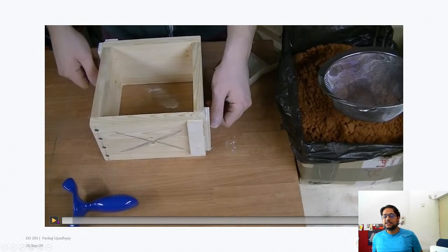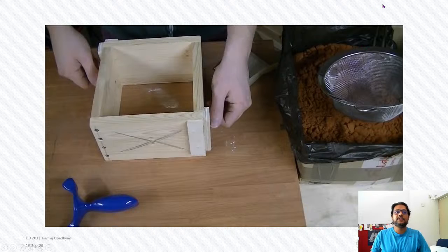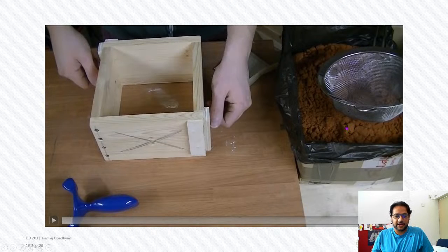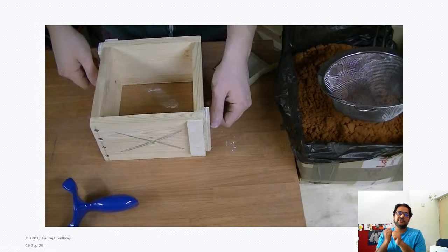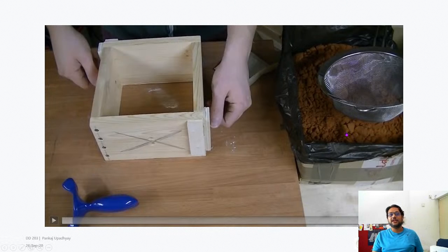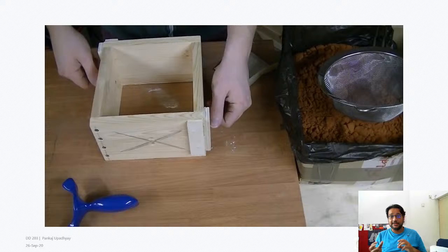So notice this carefully. On your right hand side you will have the sand, okay, and the sand has a certain texture to it. Had you been here, I would have actually shown you what the sand feels like, but now you can only see it visually, right? The sand is not entirely dry, it is slightly wet. Generally in green sand casting, there is sand and some form of binding agent mixed with the sand at a certain ratio.